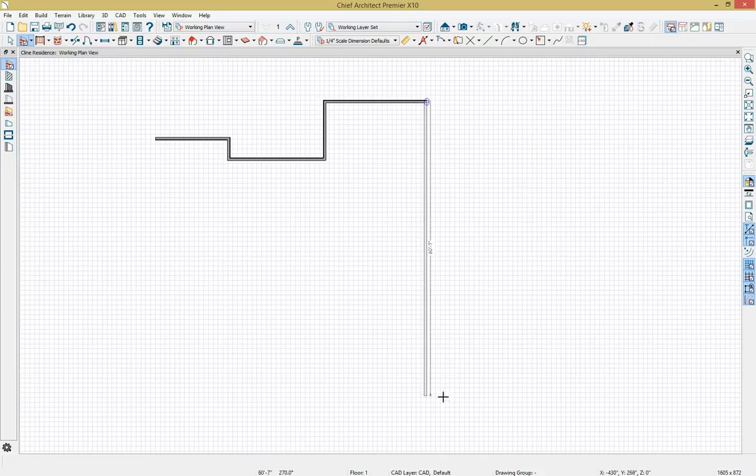And I'm not trying to be too specific with my dimensions right now because we'll come back and edit these later. And notice that as I drag this wall down here I get a blue coplanar line letting me know when I'm evenly across from that wall on the other side. So that's just one quick and nice efficiency feature in the program.